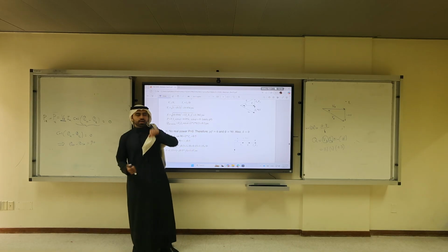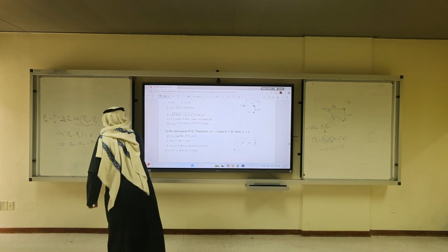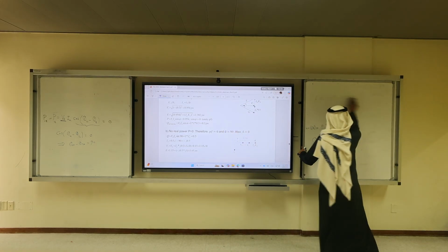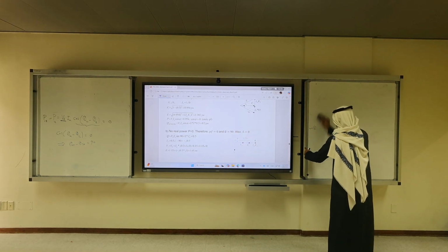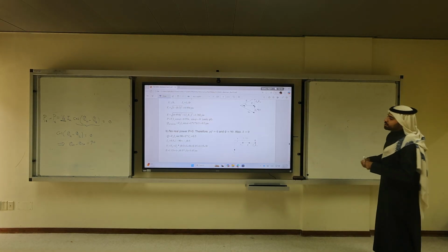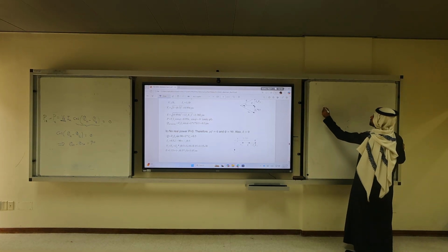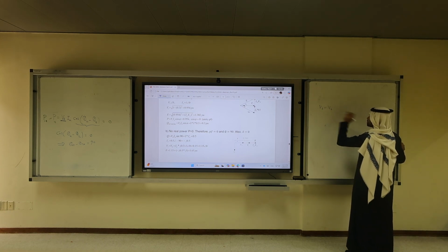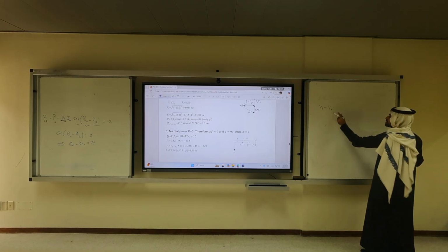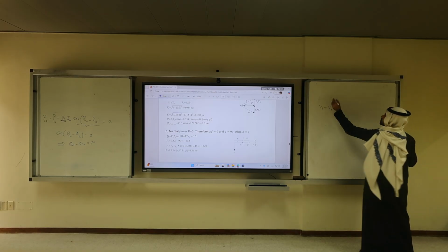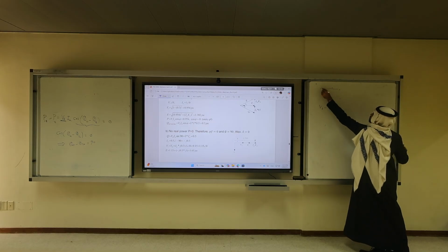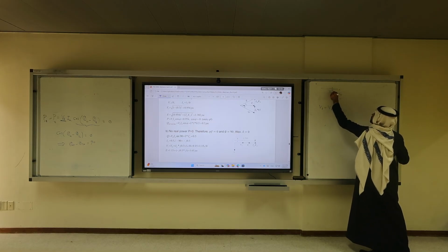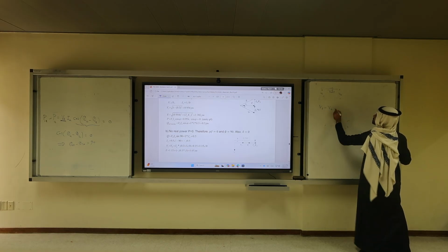We have to go back to the original equation. What was the original equation of our diagrams? Vt is equal to Vb, was it minus? Sama, what was the equation? This is Vb, Ia, 0.3. This is Vt. What was the original equation? Vt is Vb plus j0.3 Ia.